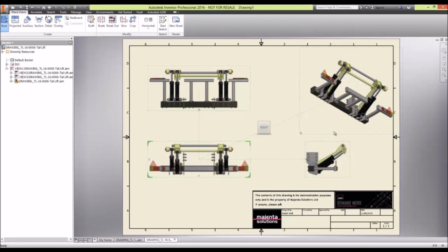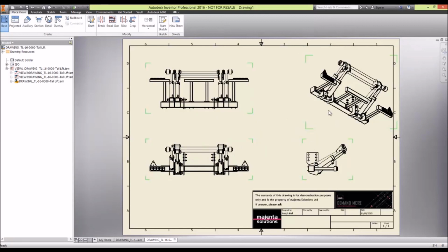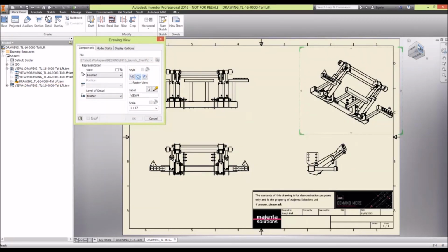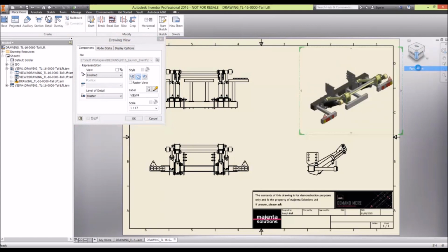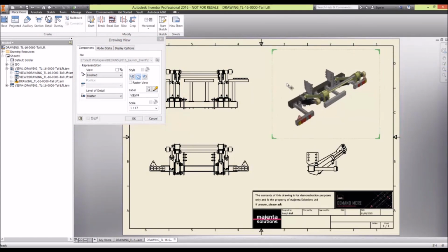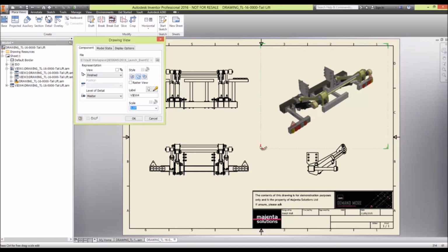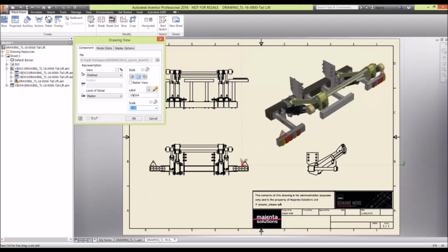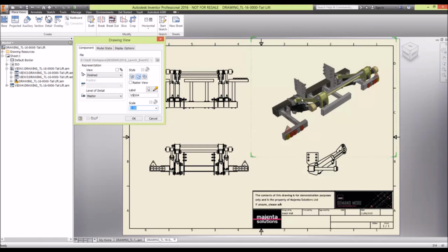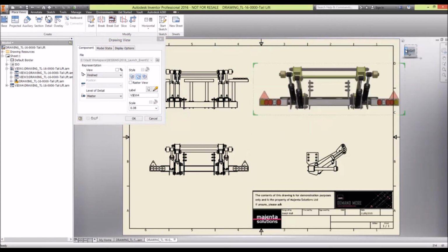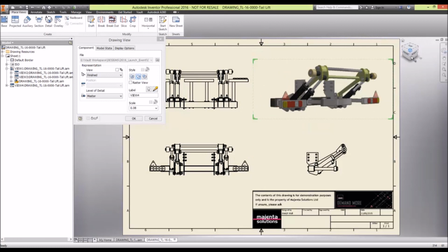And then when that's finished, what I then get, if I want to select a different view, maybe this is going to be our ISO view, so we want it to look slightly different orientation, we can right click, we can view that in perspective, I can move it out, maybe rescale it to get a different scale factor for this particular view. So you can see that's really, really easy to be able to manipulate, pick a different view, pick a different orientation, see what we've got.